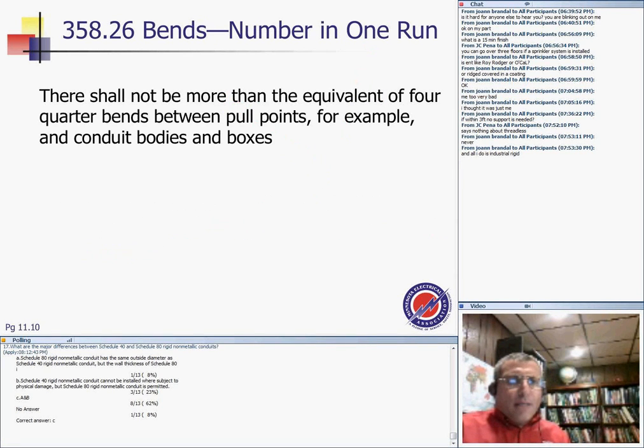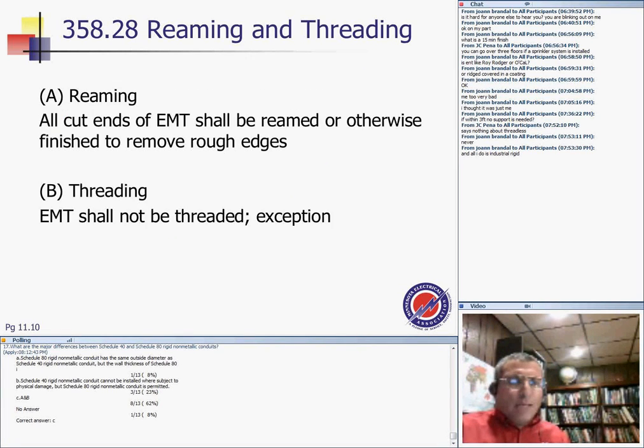Work that one. As you run it, the same thing, 360 degrees, or provide your own box and so forth. All cut edges of EMT shall be reamed or otherwise finished to remove rough edges, guys, as we all know. Can I thread an EMT? Of course, you see it. Look at that. What does it say?